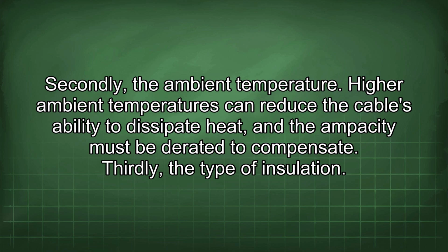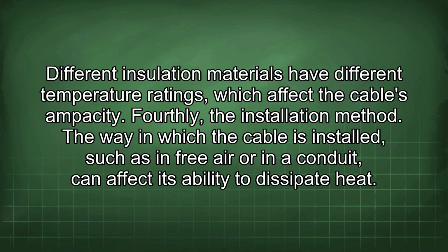Thirdly, the type of insulation. Different insulation materials have different temperature ratings, which affect the cable's ampacity. Fourthly, the installation method. The way in which the cable is installed, such as in free air or in a conduit, can affect its ability to dissipate heat.